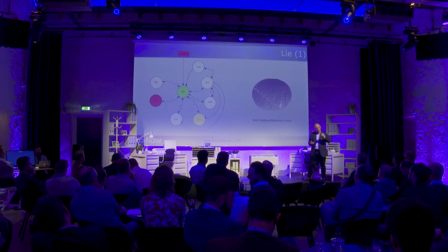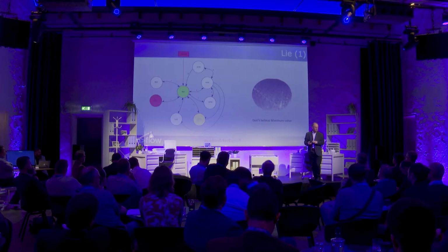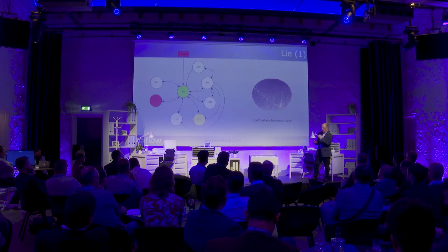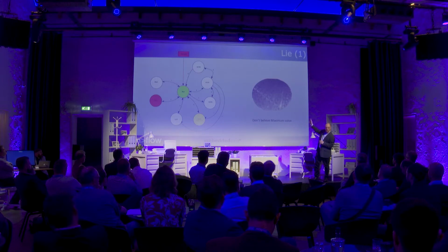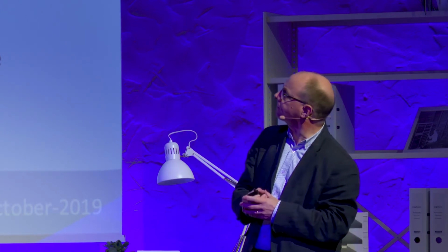Okay. Well, here's the first lie, okay? Here's the first misleading information from the supplier. Don't believe the stop mode currents, and don't believe the maximum currents that they put in the data sheet. This is a wafer, so let's talk about a 90 nanometer process. And here's a chip, there's a data sheet from a 90 nanometer process. And look, well, 1.98 microamps in the very low leakage stop mode 3, whatever that is.